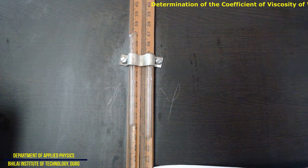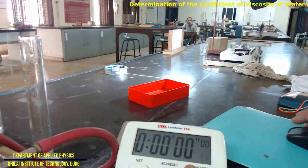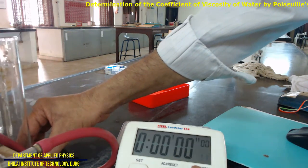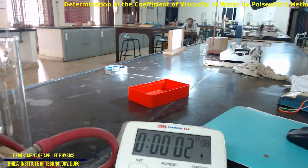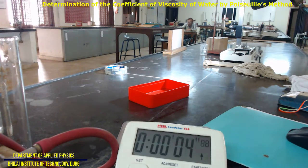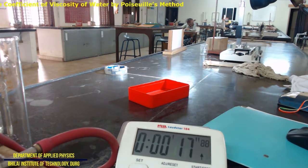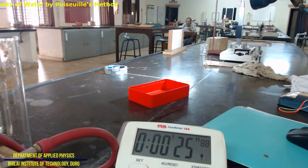For this, what we do, we are just going to insert it below and start the stopwatch. Both things are simultaneous. The process will continue for 1 minute. The water is getting collected inside the beaker, and ultimately after 60 seconds we are going to pull out the beaker and switch off the stopwatch. So in 1 minute the water collected will be obtained inside the measuring cylinder.